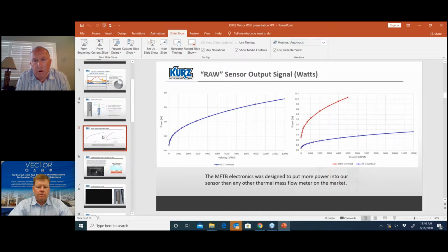And so for explosive atmospheres or environments, for say Division I applications, the assumption is that the meter has failed and is giving full power onto the sensor. So the auditing agencies don't give you any credit for your smart electronics that will shut itself down during these fault events.